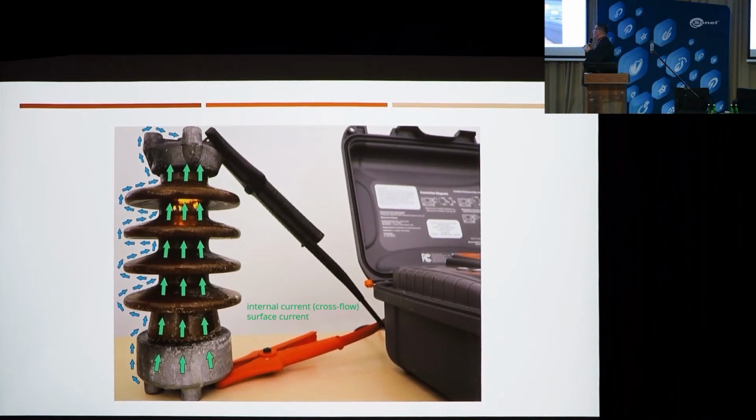We'll also be measuring something else that's a result of the current flowing over the surface. A current I'd call parasitic, but it still gives us some idea, because if we detect that this phenomenon is occurring, then we can decide, for example, that the insulator needs to be cleaned.